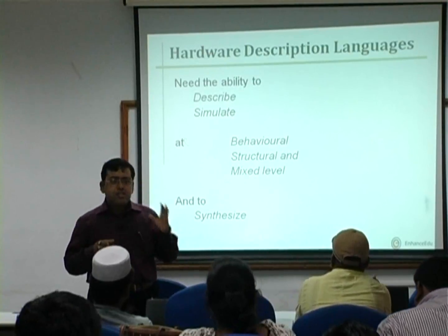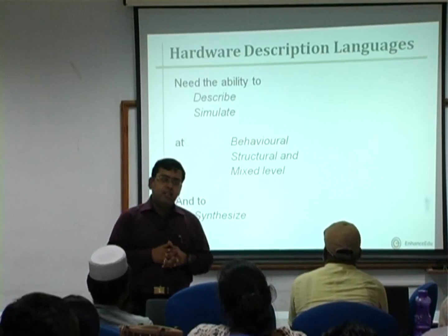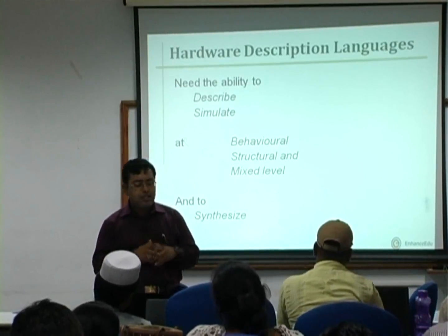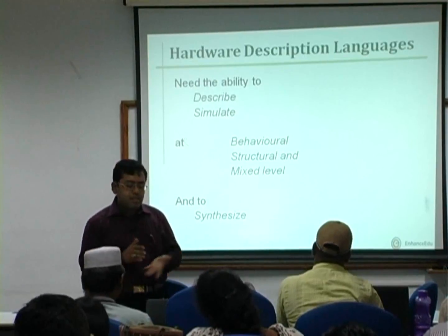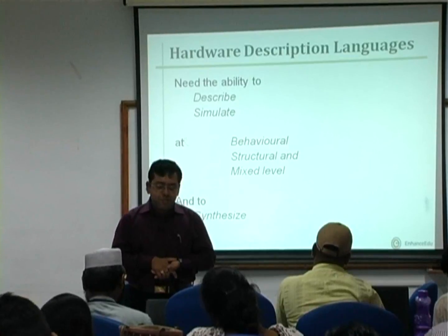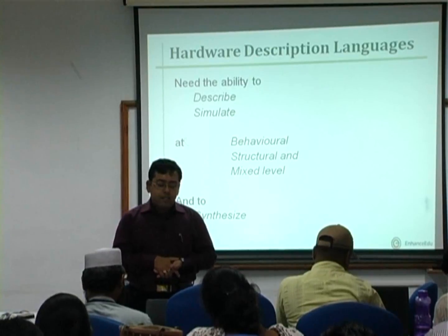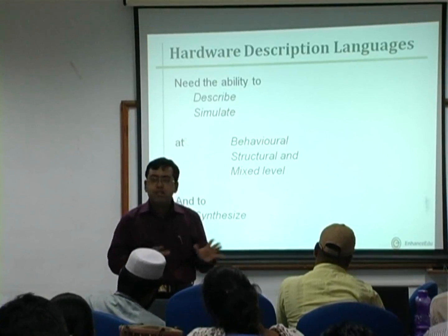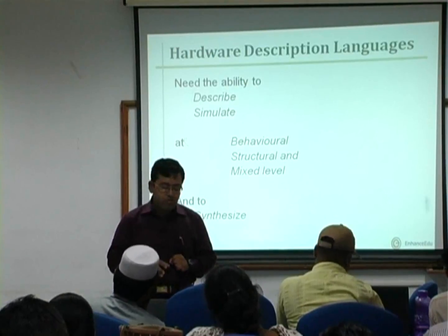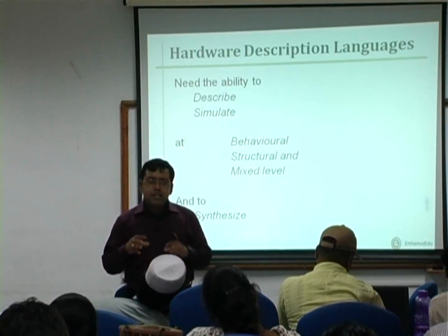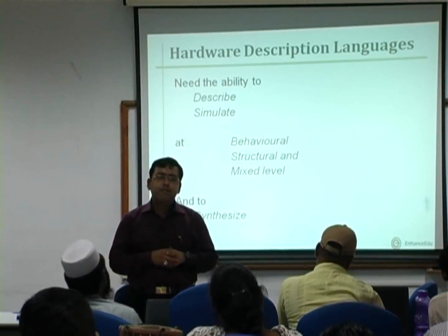So with these constraints in our mind, we define a hardware description language as one that has the ability to describe and simulate at various levels like structural, behavioral, a mixture of structural and behavioral, and then synthesize a circuit from it.